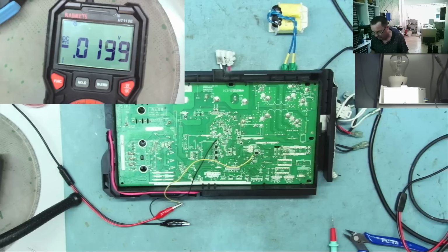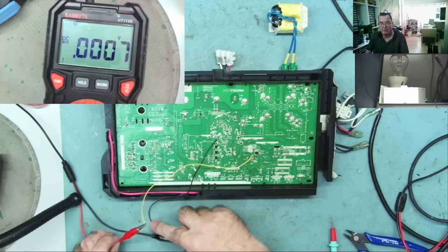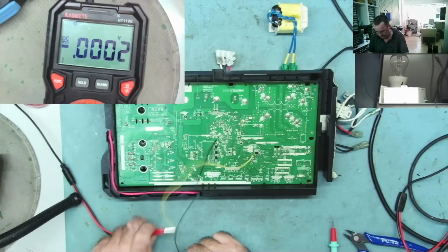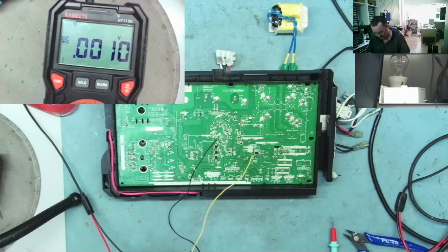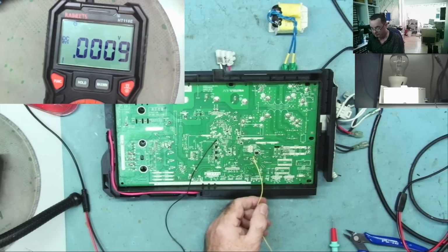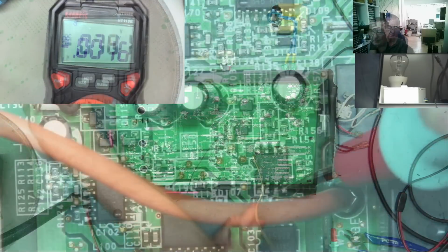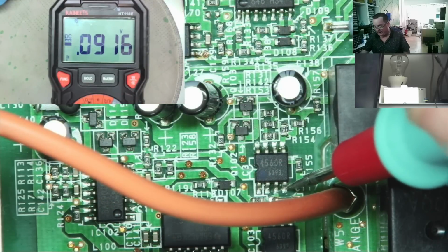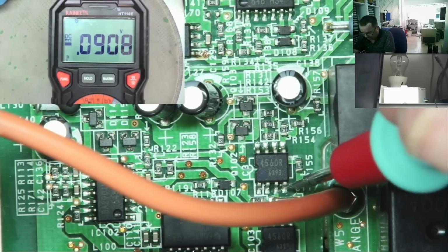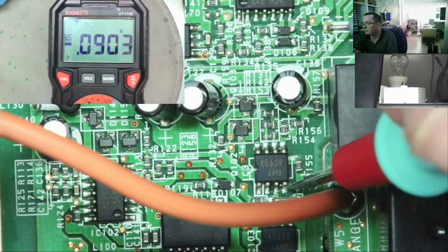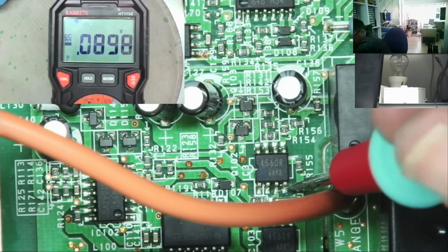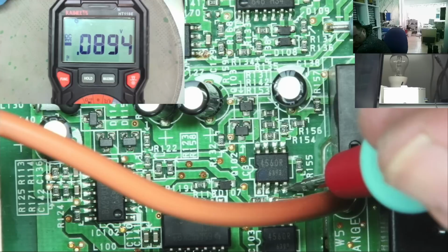One other thing I'd just like to check, and that's see what voltage is on those op amps. That I think should have a plus and minus supply. Let's see. Well, it shows a bit negative anyway. If this is what I think it is, there should be a minus supply on here. So we'll just power it up again. Nothing shorting, okay.